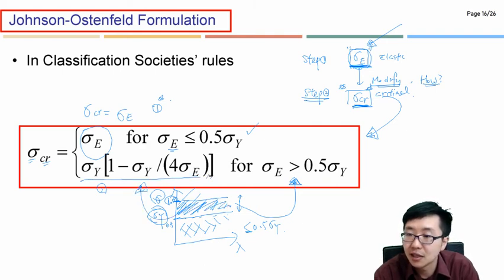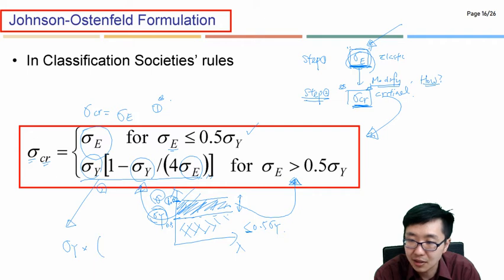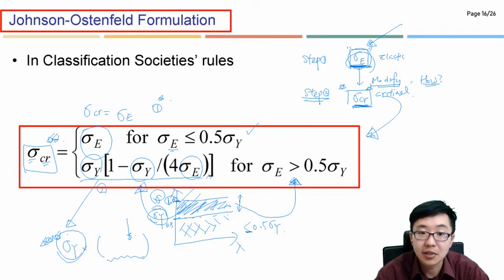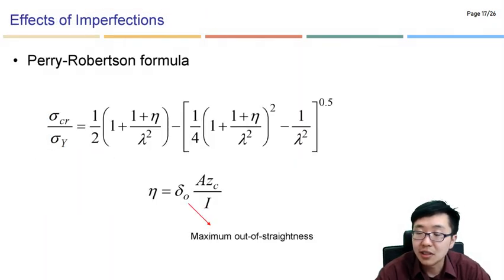It's not difficult. As you can see here, take the elastic buckling strength, substitute it here, along with the yield stress. The physical meaning is the yield stress times a certain value to consider degradation, so it will be adjusted slightly. That will be considered as the critical buckling strength. You know what I'm saying? Here is another existing formulation used in the shipyard, considering the effect of imperfections.